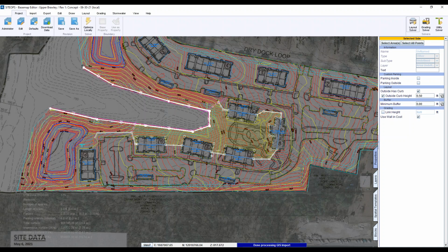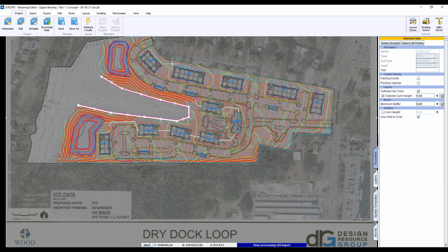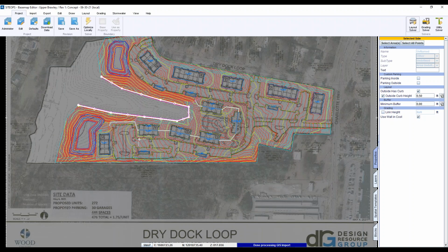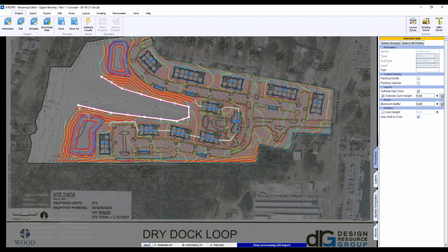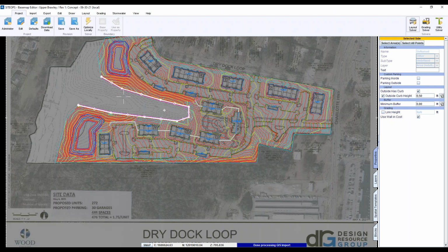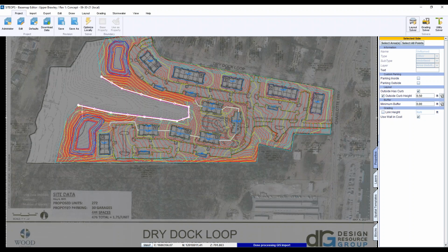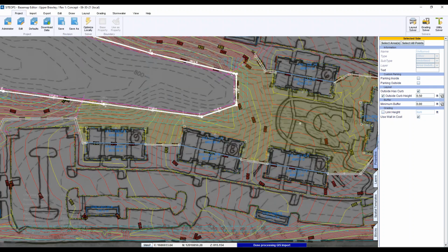So we can visually see that everything's kind of coming into the swale here, and in order to make the grades flatten the way we need for an apartment, we may very well need to put a wall in here in order to flatten that grade. So I just went ahead and drew the wall, just a potential wall around that swale that's on my property boundary. I think, let's see if I have anything else. Let's see, maybe.